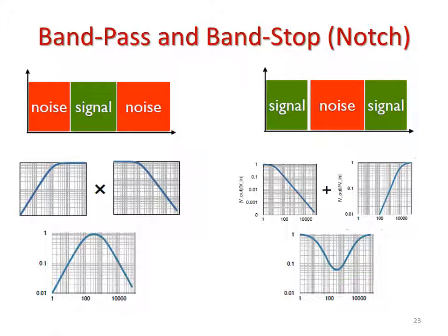It's the most useful because usually you're looking at a set frequency range. For MRIs, you're looking at a frequency of around 128 megahertz because that's the oscillation or Larmor frequency of water. So I want to include most frequencies right around that range, but anything way above there I want to block out, and anything way below there I want to block out. And that's how we do it with the bandpass filter.